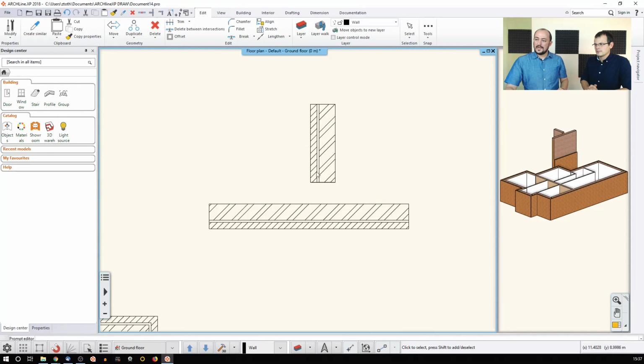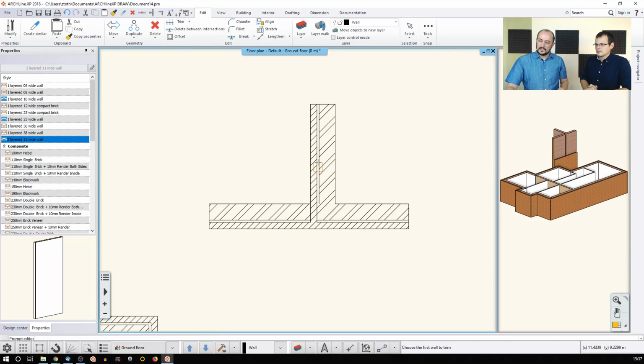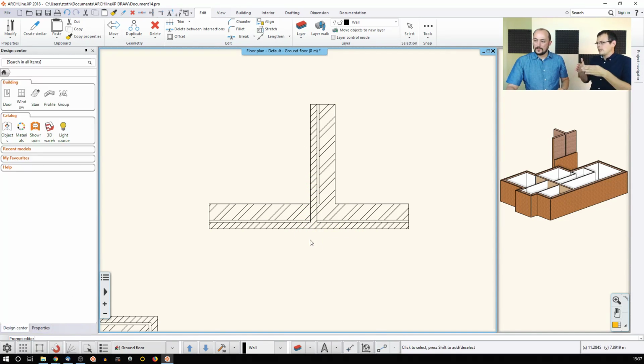So now both walls have this layer with an importance of 6, more important than the rest. So if you T-connect them, see now it's cutting through everything and goes through to match the other one. So what you're saying is that if you want two layers to meet, you have to give the same function to them. Yeah, the same, at least, and something which is higher than the layers they have to cross. Yeah, it will cross the other one if it comes to a situation like this.